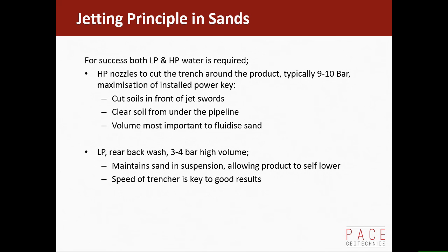It is best to have a high pressure, low pressure system. It's much more efficient in terms of power. And I've said most of that. The only other thing I would make is speed of the trencher is key to getting good results. The trencher wants to be progressing as smoothly as possible, not speeding up, slowing down, because that would cause the sand to consolidate at different rates or different distances behind the trencher, and then you get straightness incidents.